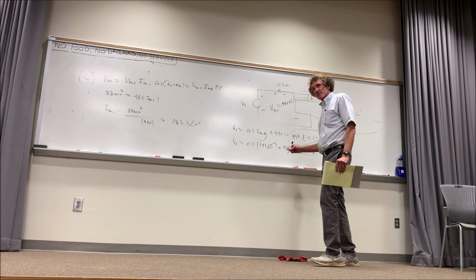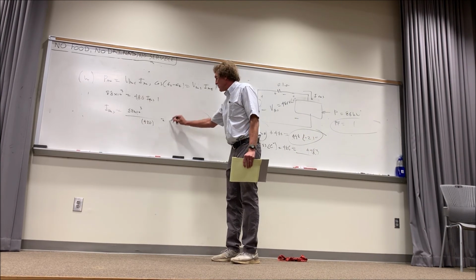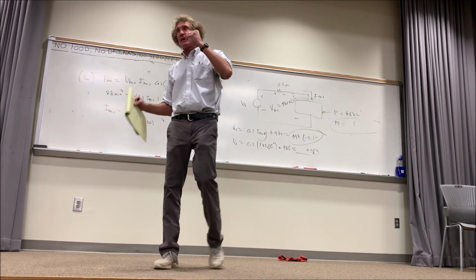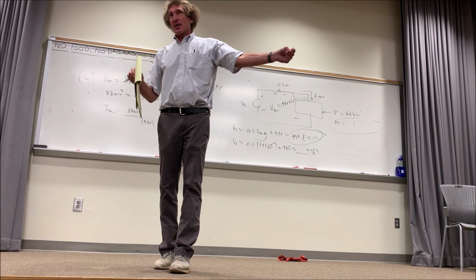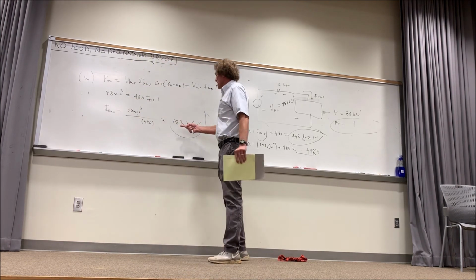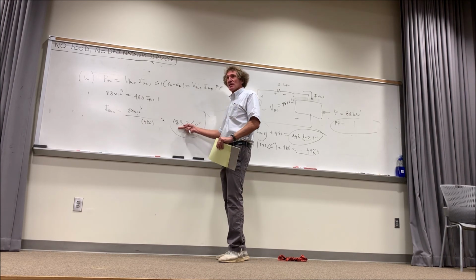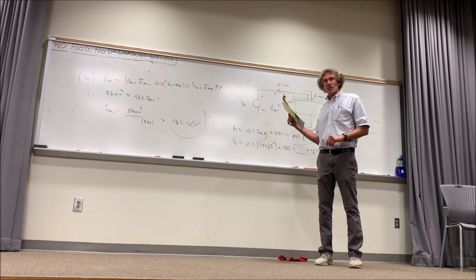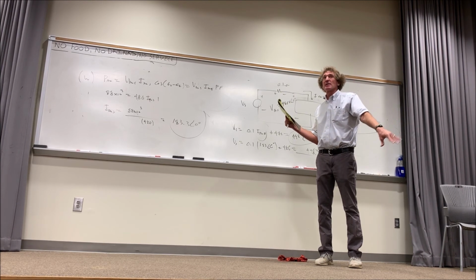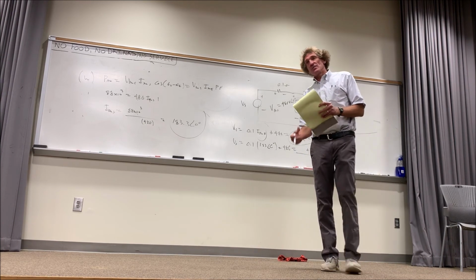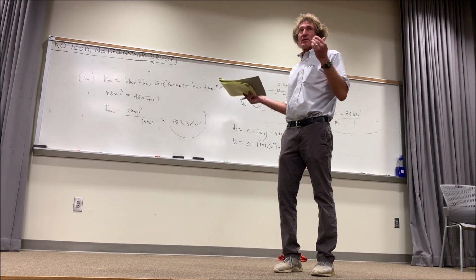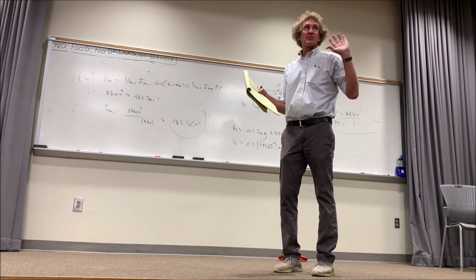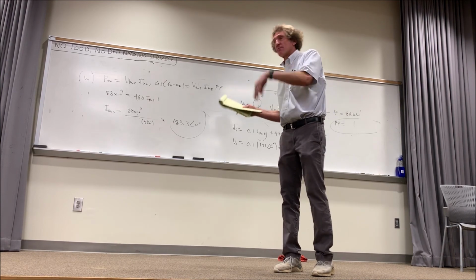The thing about this is how much less is the current? It went from 253, right, down to 183. Now, if you think about the power supply, voltage times current, right, the power, the amount of current here, 183 will have a lot less losses in the line than 253, or whatever it was, follow me? Because the lower the amount of current that is required to get the same power, the better it is. And that's why industries will fine you if your power factor is below a certain level. And they measure this. I don't know all the laws, but I know that in major industries, power factor is super, super important, and they have ways of taking care of it.